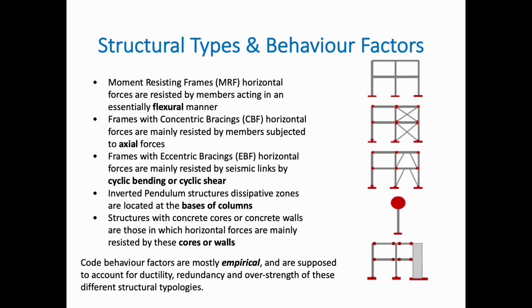Before we go to the behavior factors and how these are presented by Eurocode 8, let's again synopsize the structural types. We have the moment resisting frames, which resist the horizontal forces essentially by flexure of the members. We have the concentric braces, in which we have axial forces in the members, tension and compression, as we discussed before. We have the eccentric braces, and we mainly focused on the seismic links, with cyclic bending or cyclic shear of that link element.